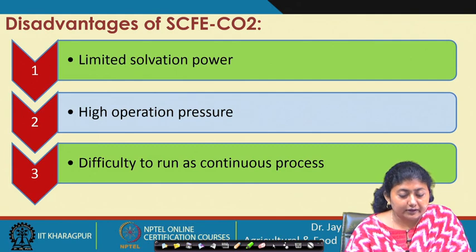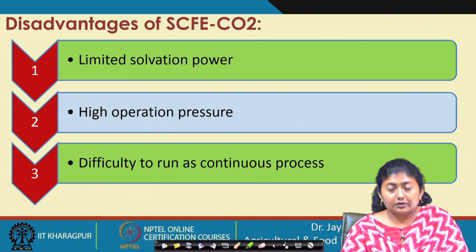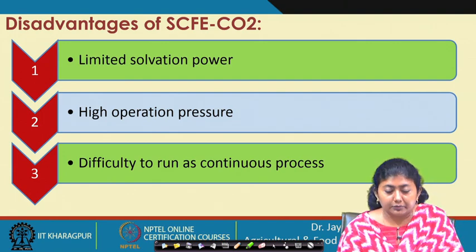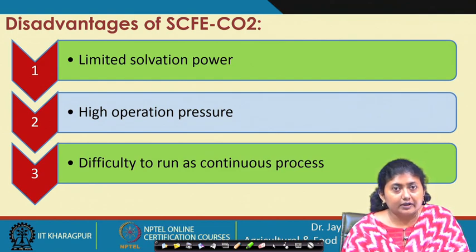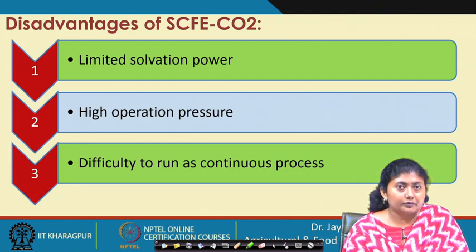The ideal case is that when we go for an extraction or leaching process, the energy needed in the extraction is very less, but the energy needed in separating the solute from the solvent, or the solvent from the solid slurry, is huge, because there we need to apply evaporation or distillation, which are very energy intensive techniques.